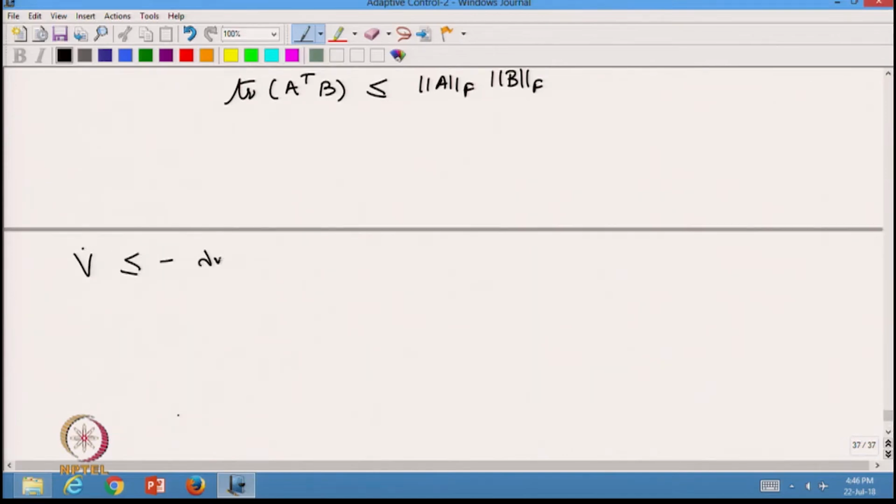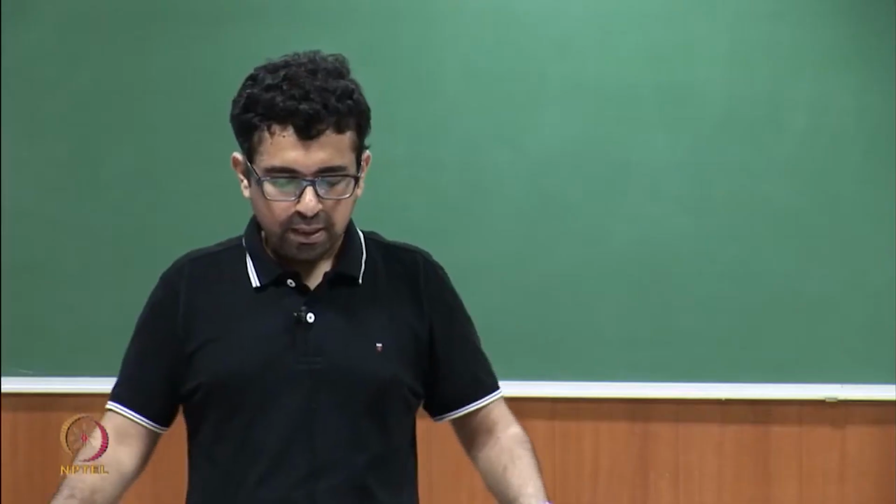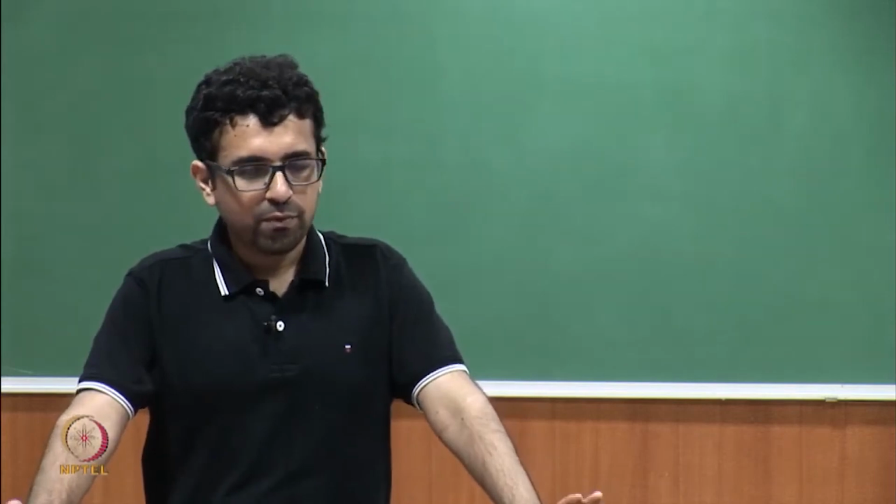The first term we can upper bound like we did before, and we can also take the upper bound of the second term, which is the disturbance term, by using the maximum eigenvalue of the matrix P times the upper bound of the disturbance d bar times the norm of E. Although d bar is not known, it is okay for this to appear in the Lyapunov analysis, as long as it does not appear in our control or adaptive laws, it is fine.